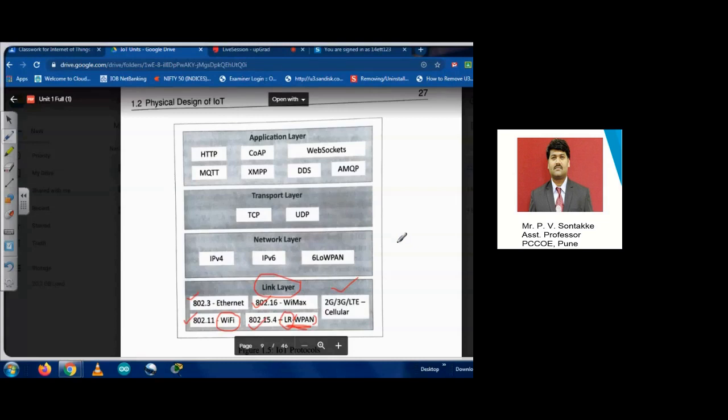And in 5G, we are using MIMO kind of communication, the aerials, multi-input, multi-output, and the frequency used is up to 30 gigahertz. The data rates we can achieve will be more than 1 Gbps. Here we can use the access technology OFDM, orthogonal frequency division multiplexing, through which we get the maximum amount of data. Okay, so these are some details, a brief introduction about the link layer contents.